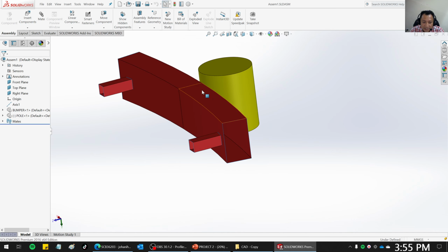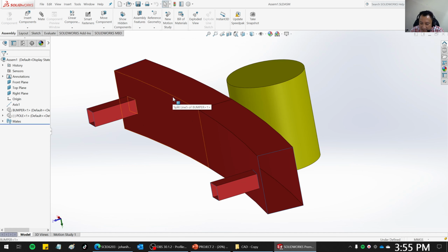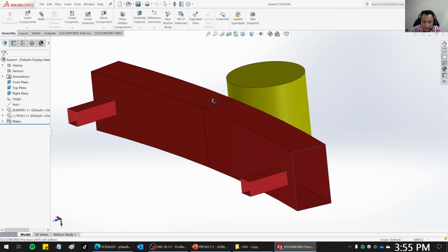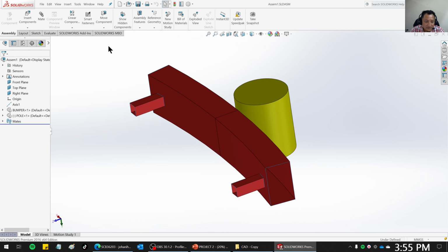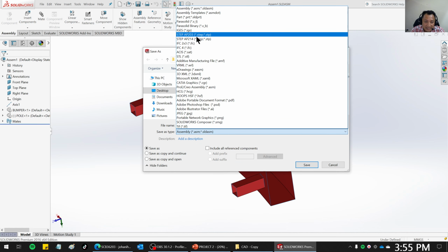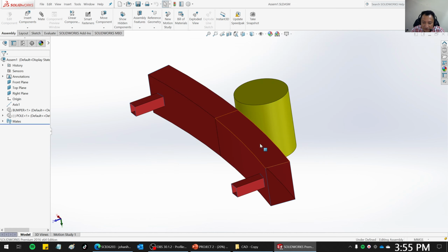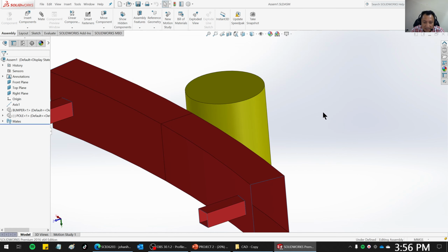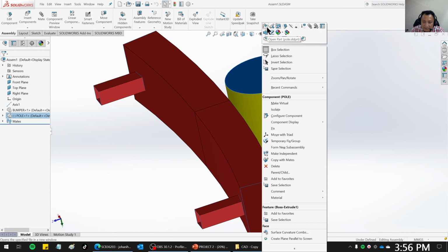So in order to proceed, we will be doing Ansys. If you want to export your geometry to Ansys, you need to first of all go to file, save as, into step file. But before we do that, we need to modify something. Number one, which is this pole. So I can right click and then open up the pole.